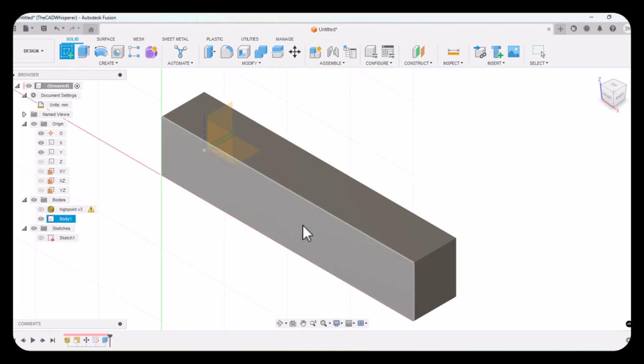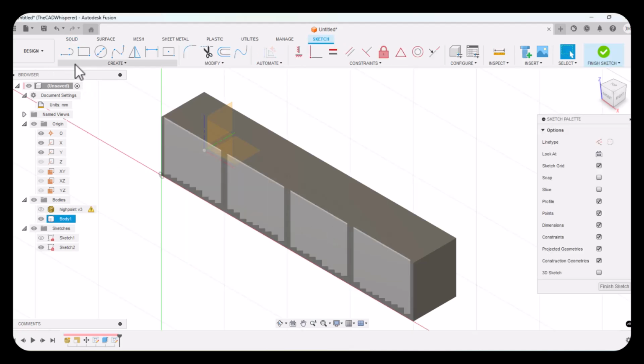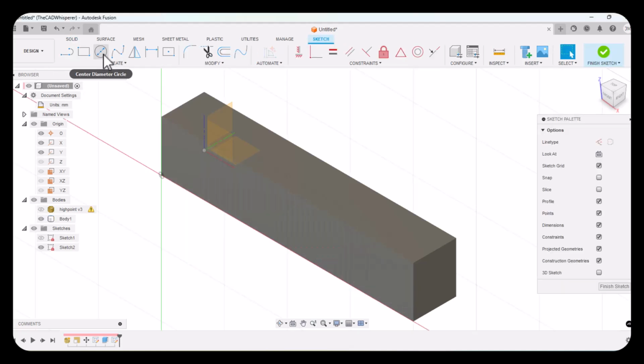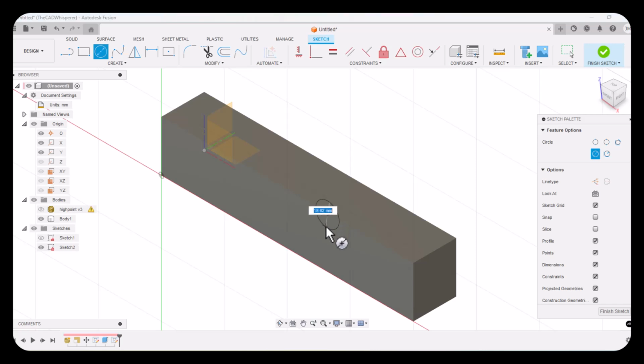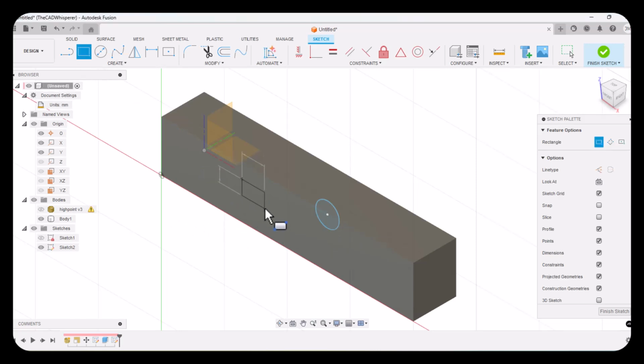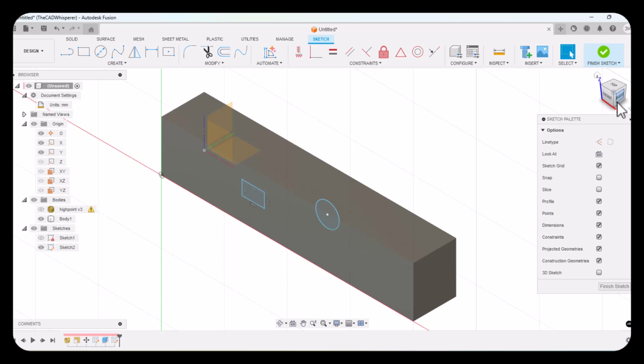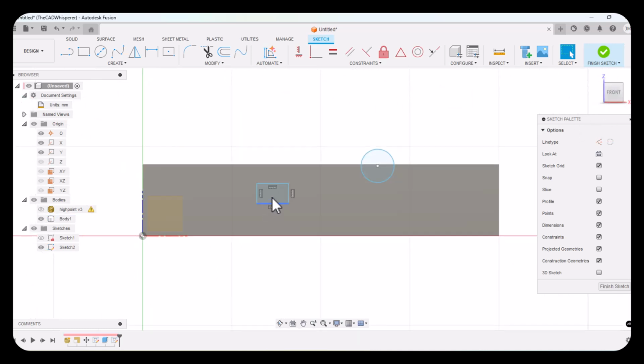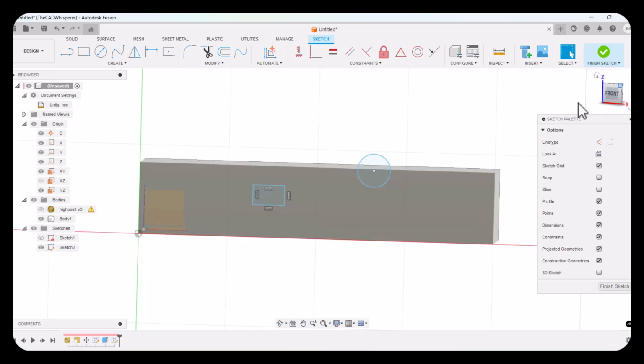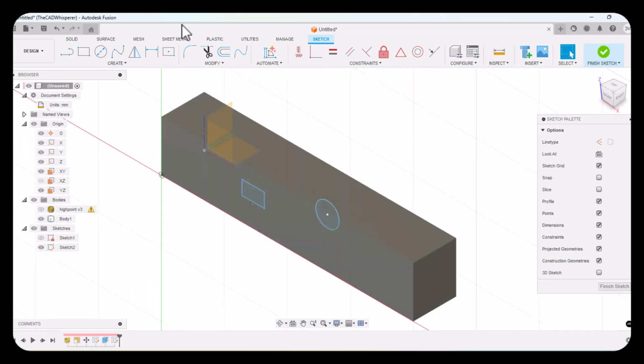And so I'll do a sketch on, say, on this face, and maybe I want to do some kind of feature up here. Maybe I want to do some kind of feature here. Now, don't leave your geometry as blue geometry. Blue geometry, white dots should drive you crazy. Put dimensions in here to fully dimension the features that you're trying to make. I don't know what features we might want, so I'm just going to leave that the way it is.